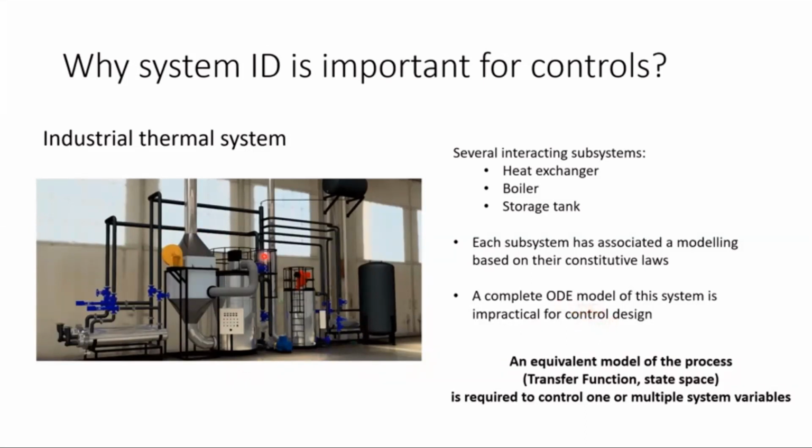So the ODE modeling in this case, for, let's say, temperature control, could not be the best approach. The best way to proceed is to find an equivalent model of the overall process, based on the input and output that we want to control, in terms of a state space or transfer function, which are the linear models that we see during the class.